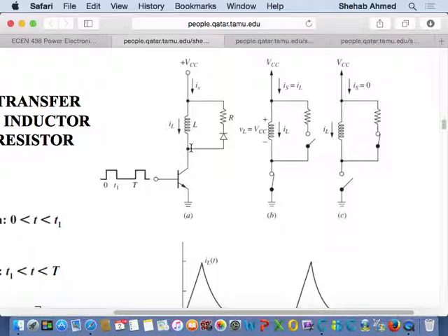So we create a bypass circuit, or a freewheeling circuit as we call it in power electronics terms, for the current to flow. The inductor current will never change direction instantaneously. It was flowing this way, and it will keep flowing this way until it's dissipated, right? It goes down to 0. So where will it flow? We put a diode here. How does the diode turn on? If it sees forward current, right?